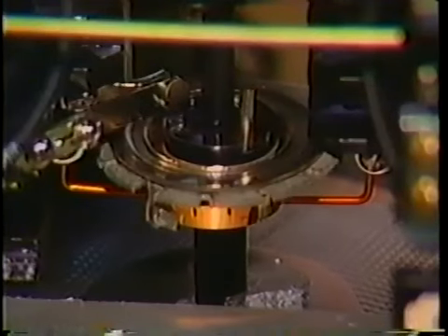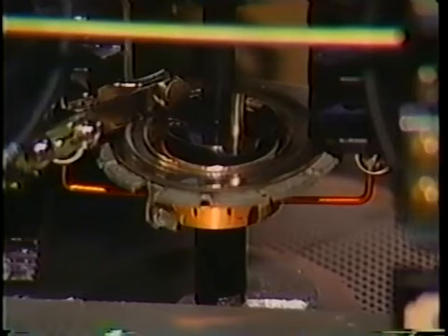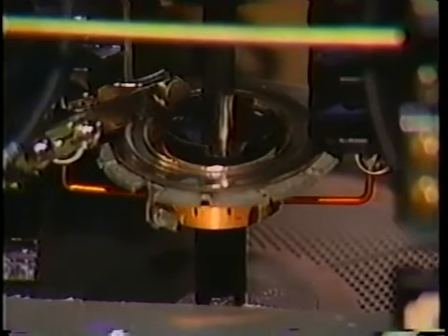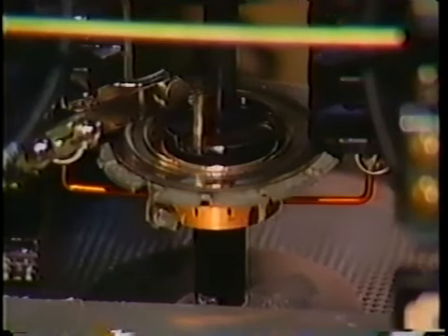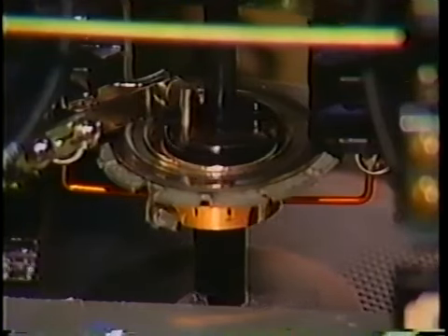Once the disk is rotating under fault conditions, inertia will cause the disk to continue slight movement, even if the current falls below pickup value. This over travel could cause inadvertent tripping.